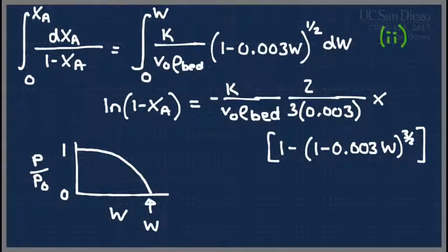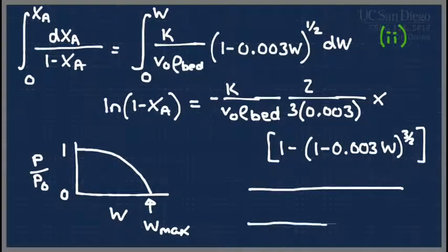That represents the maximum amount of catalyst that you can have in that particular reactor before you run out of pressure to actually drive stuff through. What this is describing is that if you were to try to turn that reactor on, the flow would initially come in at some velocity, and then it would start slowing down. So these arrows would get smaller and smaller, until eventually you hit some point here where you don't have enough pressure to drive anything anymore.